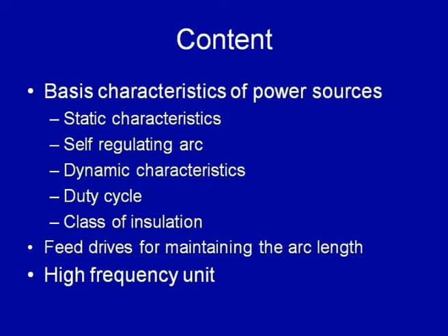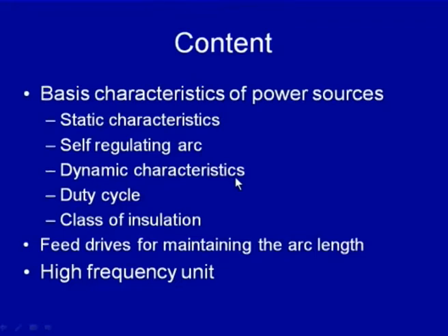So, as far as the content of today's presentation is concerned, we will be going through some of the static characteristics of the power sources, that is the constant voltage power source in association with the constant feed drive system, so as to obtain the self regulating arc. What is self regulating arc and how does it help in maintaining the arc length, and the dynamic characteristics of the power sources, which indicates how fast a welding power source responds to the changing conditions during the arc welding, especially in respect of variation in the required arc voltage and the requirement of the welding current.